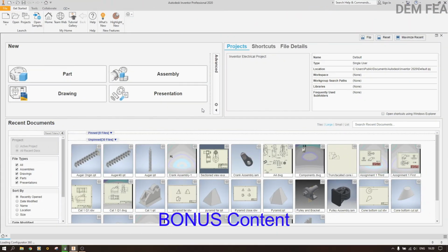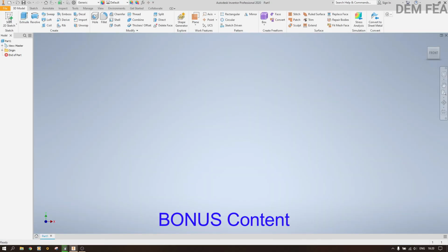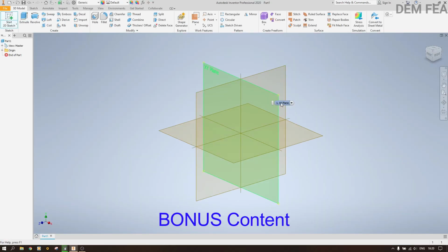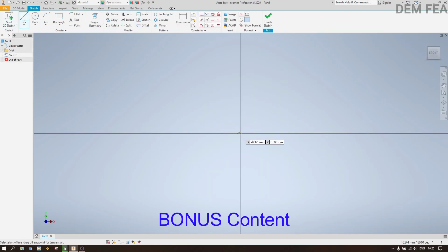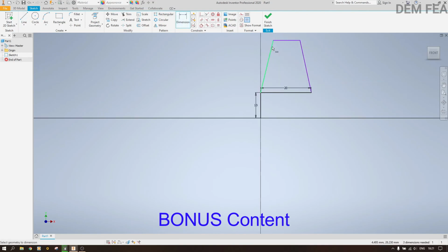So now when you are creating the CAD file using Autodesk Inventor, as you've seen, I'm choosing the XY plane. So I have to make sure that the axis that I'm going to rotate my coil is in the Z axis, and that's why I chose the XY plane. And now you see that those are my dimensions, the ones that I've used. So you can see that I have 20 and 10, that makes 30. That is for this example I used. Now this will be a diameter of 60. Now that is for this example.